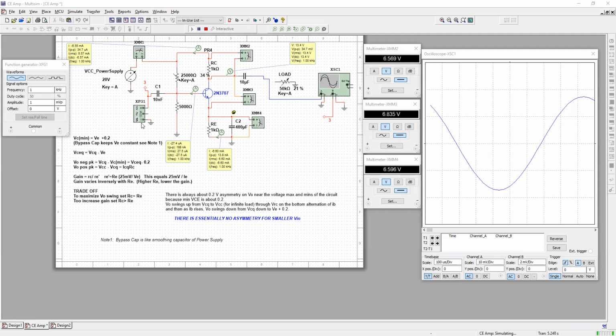The smaller capacitor, on the other hand, will tend to choke the voltages that are slower. The lower frequencies will experience more impedance at the capacitor, and therefore the capacitor will take more voltage. It will take more work to pass through that current. So a small capacitor in series with a resistor will tend to choke the voltage at that resistor at lower frequencies, of course. You would be able to get it to act like a wire again by increasing the frequency.